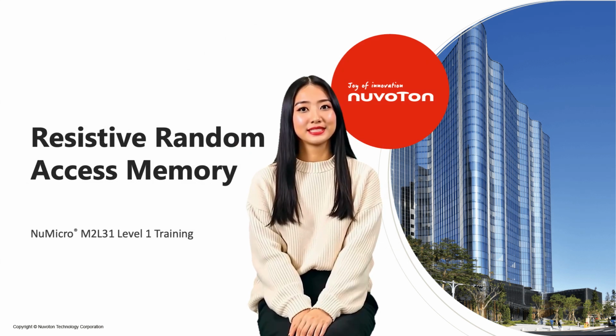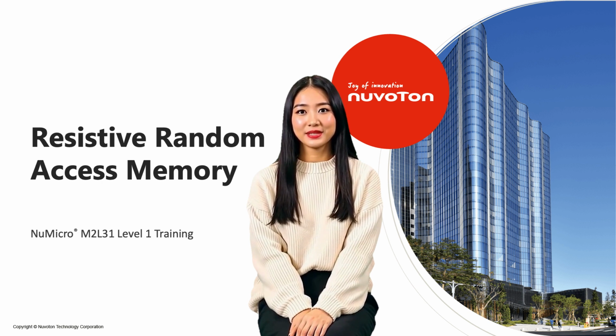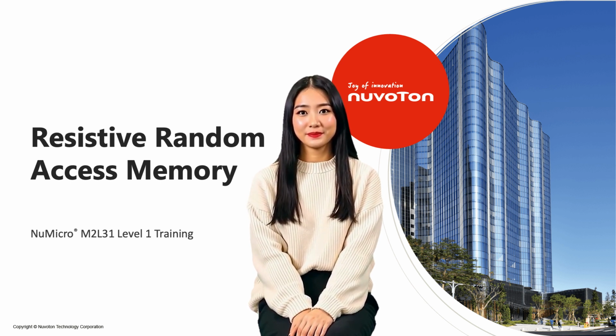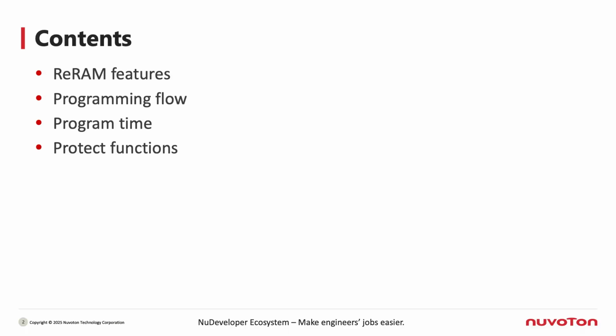Hello everyone! Today, we're going to explore an innovative memory technology, Resistive Random Access Memory or ReRAM, and learn how it is implemented and applied in the Nuvoton M2L31 series microcontroller. Resistive Random Access Memory, or simply ReRAM, is the focus of today's lesson. In this session, we'll go through the following topics in order: the key features of ReRAM, the programming process, the programming time, the memory protection mechanism, and the corresponding configuration settings.